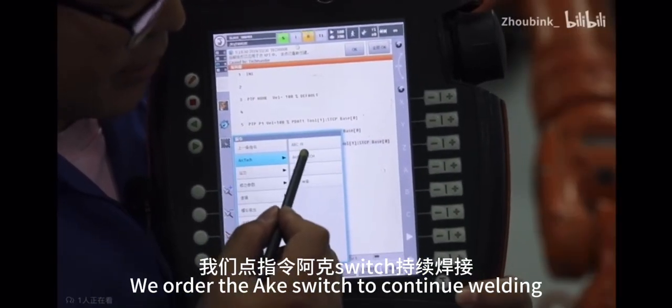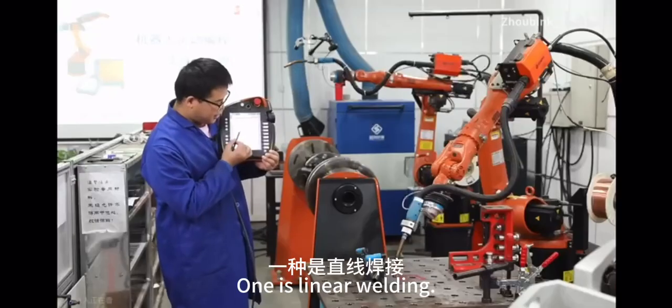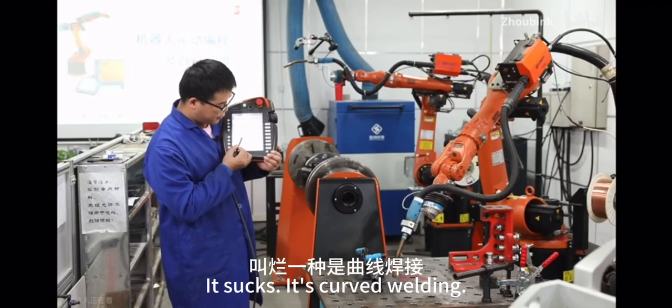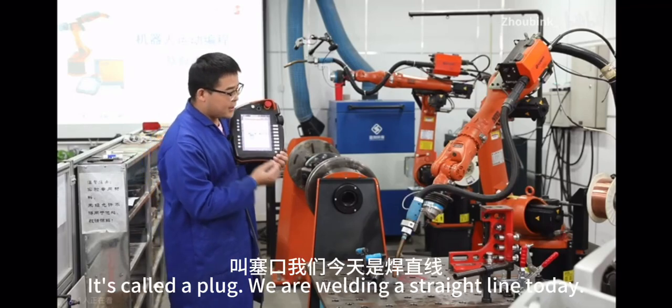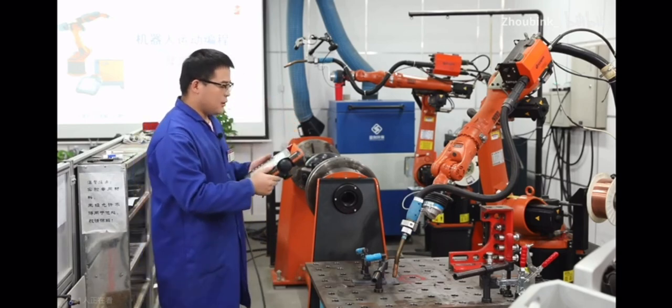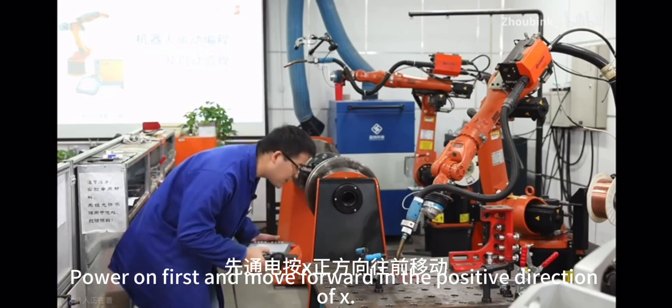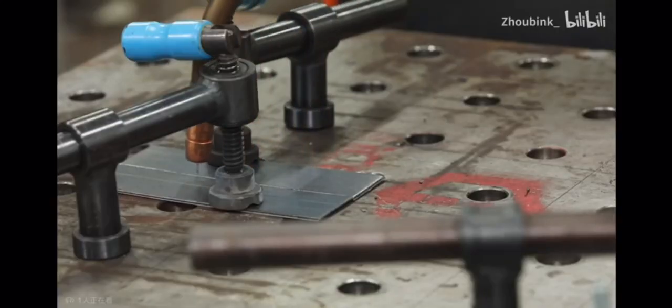We switch to continue welding. What about welding? There are two forms. One is linear welding. The other is curved welding. We are welding a straight line. Click straight. After clicking on the straight line, keep the robot moving. Power on first and move forward in the positive direction of X.